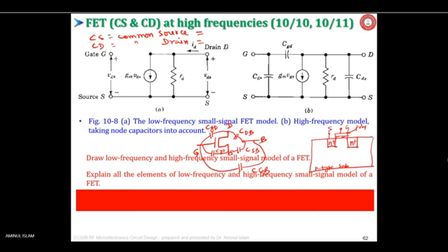This is say source, this is drain. And the body of the N MOSFET is connected to... for the sake of discussion, you can put a body terminal here at the bottom, which is normally grounded, and the source is also grounded.